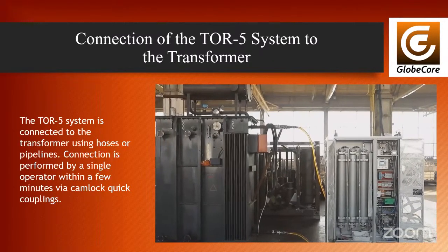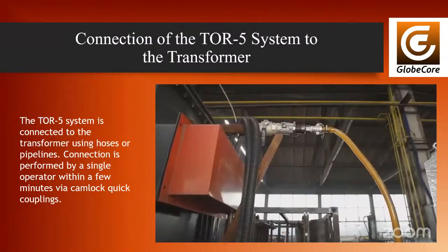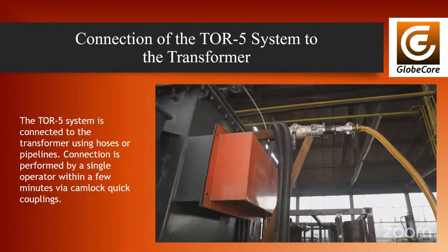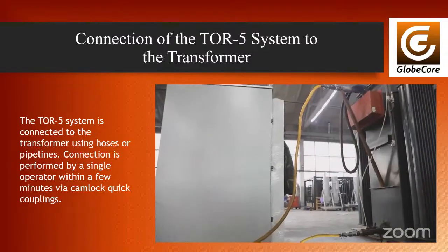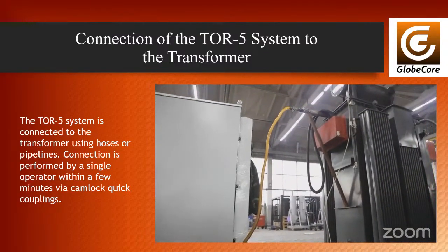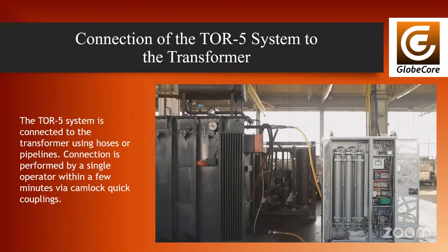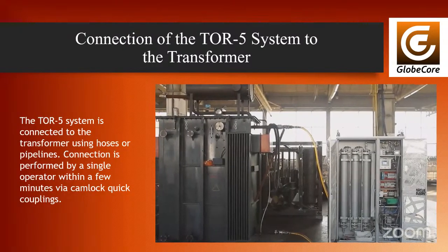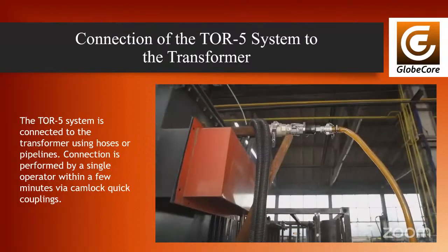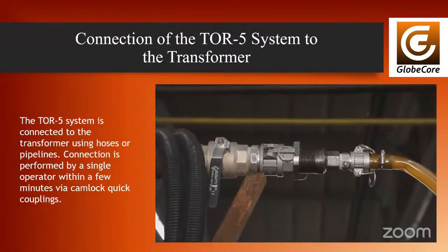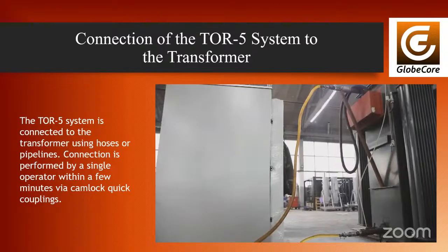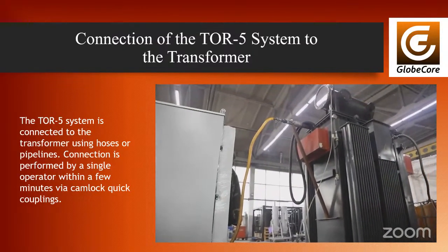TOR5 connects to transformers with hoses or pipelines. Quick-release cam-lock couplings allow one operator to connect it in just a few minutes. It can also connect directly to radiator fins. TOR5 works with any oil-filled transformer, no matter the brand or age. The temperature sensor is fixed directly on the transformer tank.